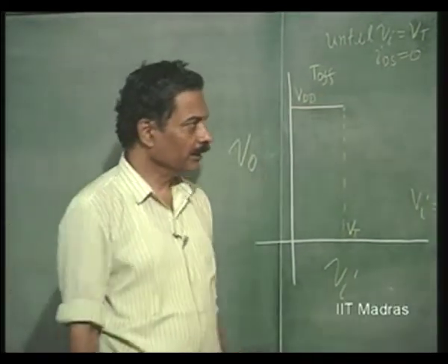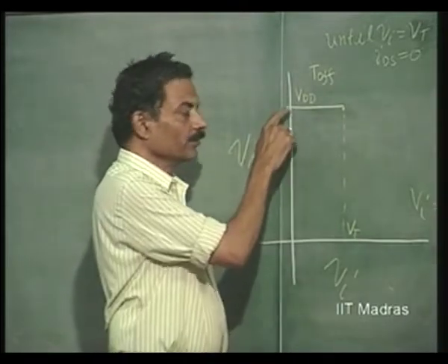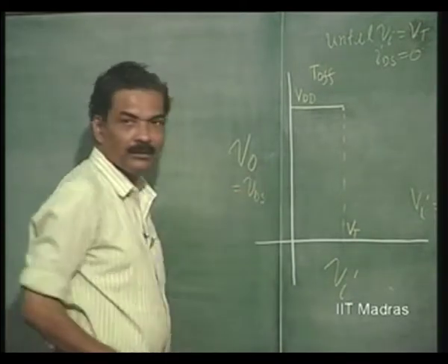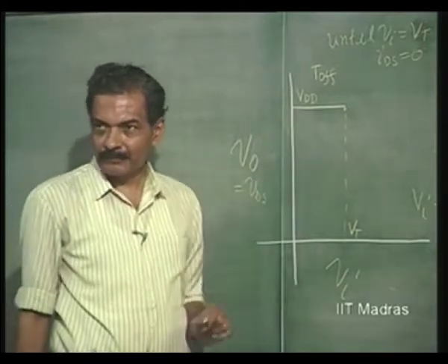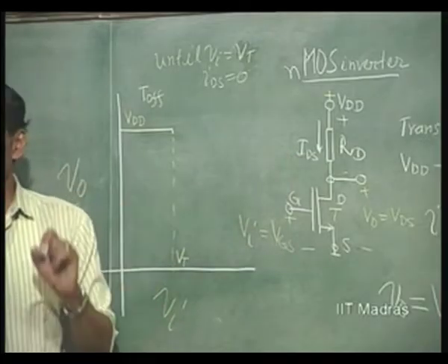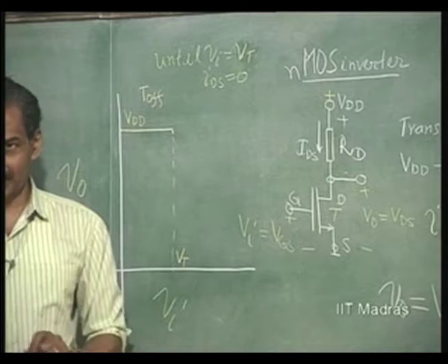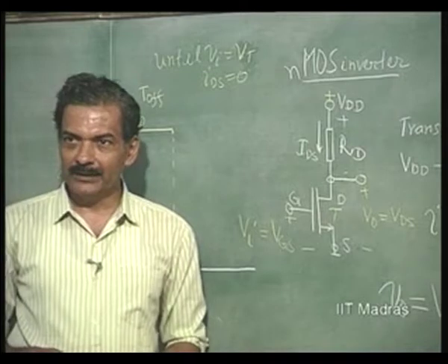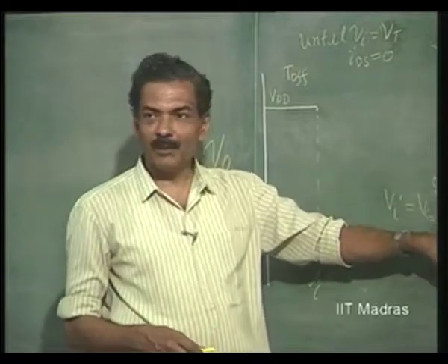The question is, the voltage Vds in this case is equal to Vdd itself, because V naught is equal to Vds. So, that is equal to Vdd, the highest voltage possible. The current is starting from 0. Is the FET in the current saturation region or triode region is my question. Have you understood the question? Where is the transistor located? This voltage is the highest possible.